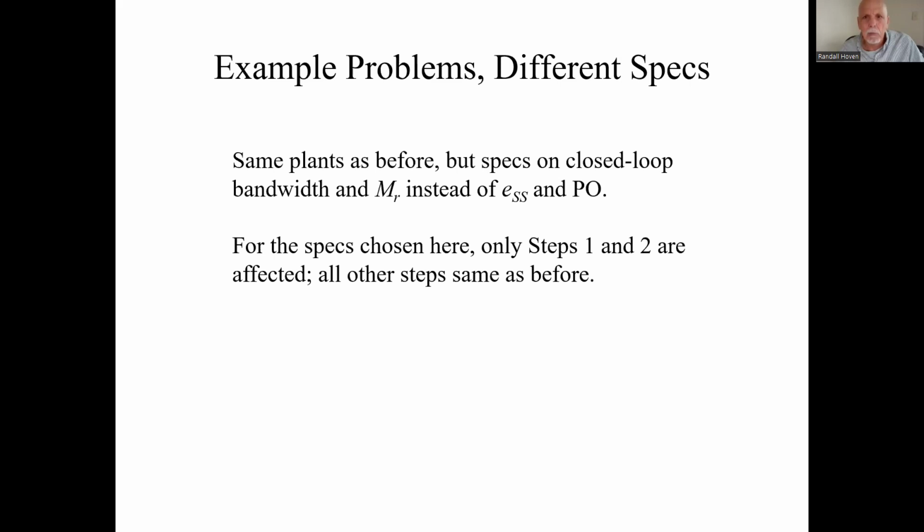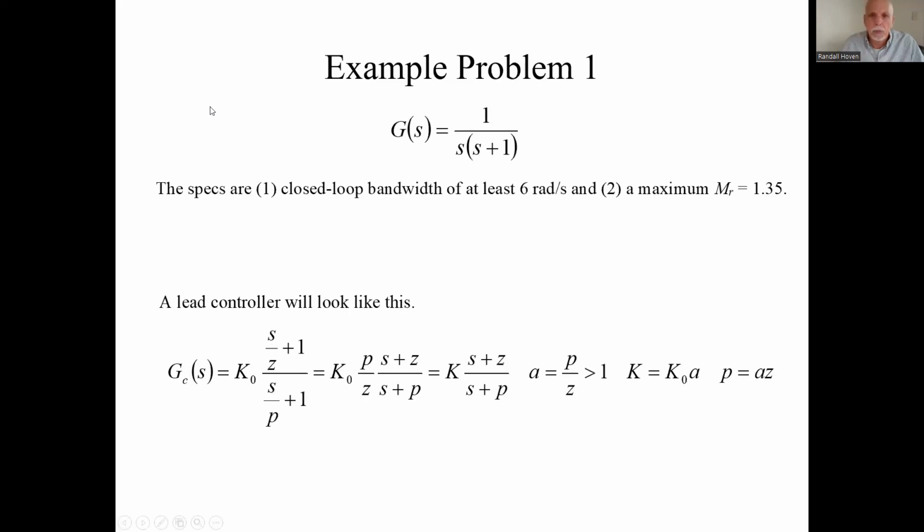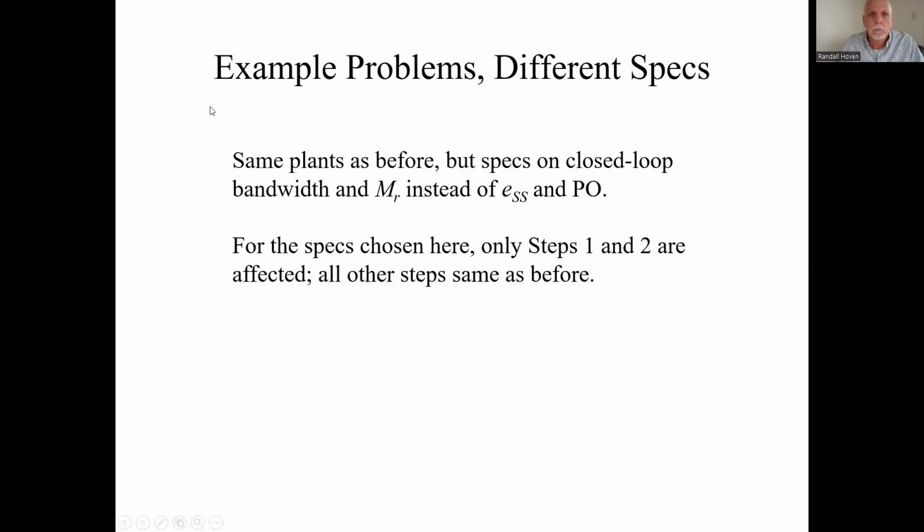Okay, some final remarks on designing a lead controller using Bode, but with different performance specs in the first place. The examples I did before had two kinds of performance specs. One was a steady state error spec, and the other was a peak overshoot spec.